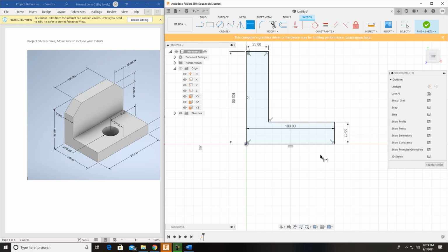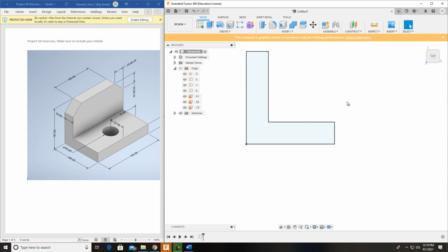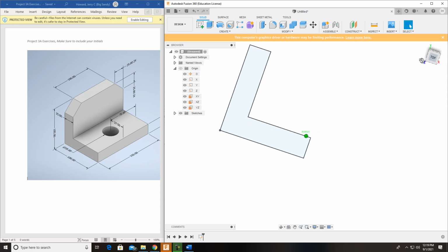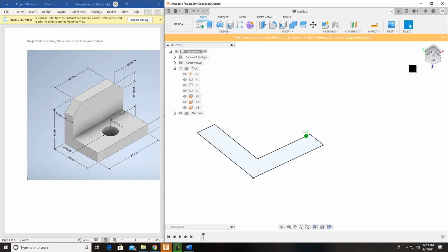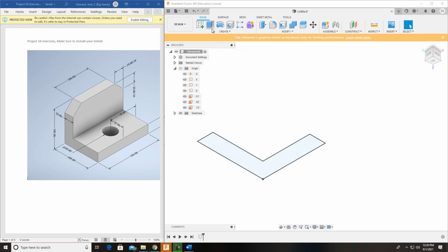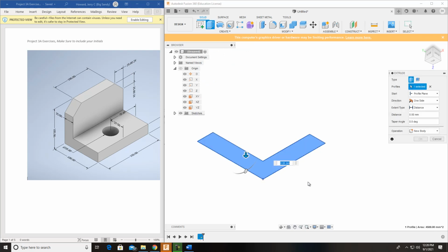You've got it. So as far as I can go on the sketch, after you get done with it, you're finished with the 2D sketch. Now you're ready to go into your feature mode. Let's add some depth. So I hit Finish Sketch up here in the upper right, and I want to rotate this thing around a little bit. And when I do that, I am right now in feature mode. I can hit Extrude, click on Extrude. And when I do that, I'm extruding this thing 150.